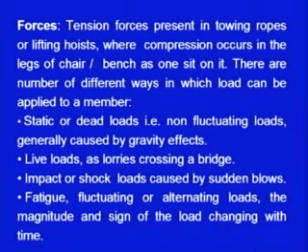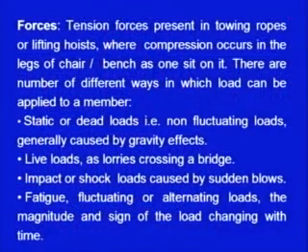Again, there are a variety of categories, under which one is static or dead loads. Static means the magnitude and direction of the loads are not changing with time. So, they are constant. Let us say you apply 10 Newton of force, or we have an object of, let us say, 10 kilogram. If you are pulling it, or sitting on a chair, then this kind of force is a static or dead load, also known as a non-fluctuating load, generally caused by gravity effects, because if you are pulling or sitting on the chair, gravitational acceleration is always associated with the mass of the object. So, that is why gravitational effects are always there under the static and the dynamic loads. Because as we have discussed, these live loads are there.